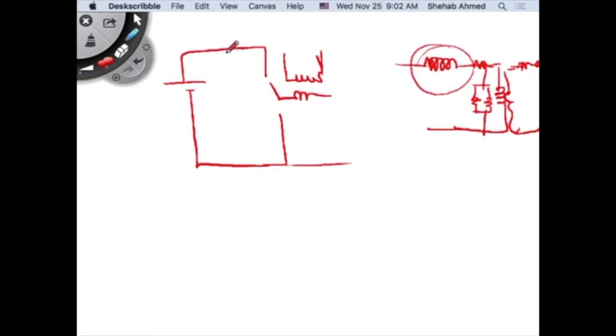So same thing, I have my two switches, have a voltage across them that is fixed. And my output is going through an inductor, right? Nothing changes. All the power electronics topologies are the same. Always the two switches that are operating complementary have a fixed voltage across them. And between them, then there is an inductive current of some sort. It can be a transformer. It can be a big inductor. It can be a small inductor. It depends on your circuit's operation, right?